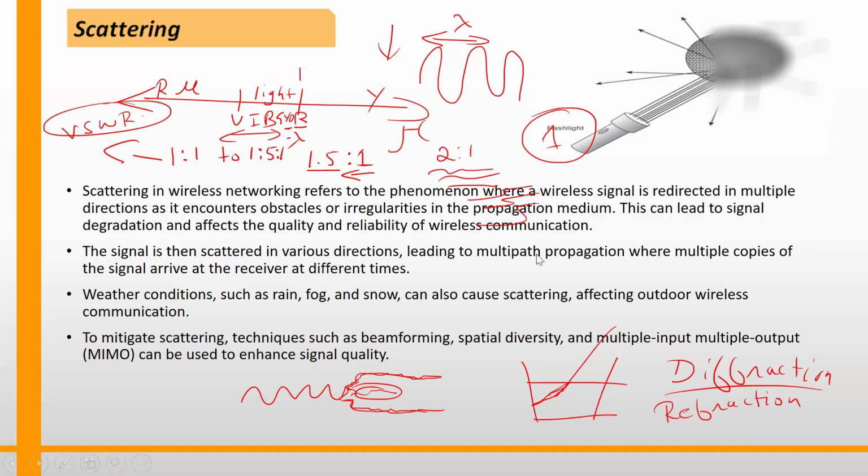I hope you got that concept. Yesterday when we were checking the data sheet, you saw that VSWR value, right? So now we know what 1:1 is. One is the maximum voltage that the transmitter is sending, and the other one is the minimum voltage that the antenna is absorbing. So Vmax is equal to Vmin.